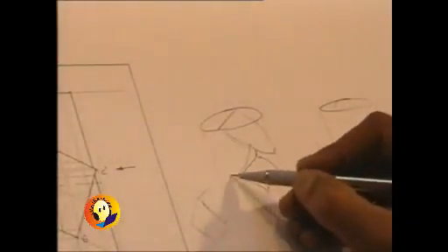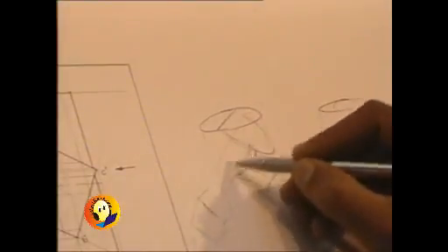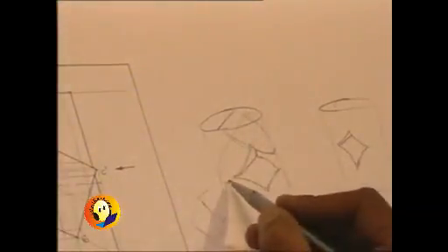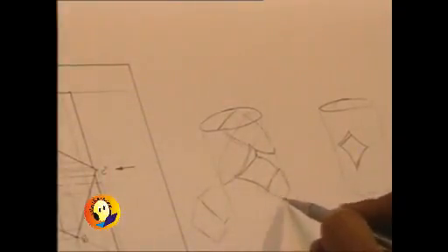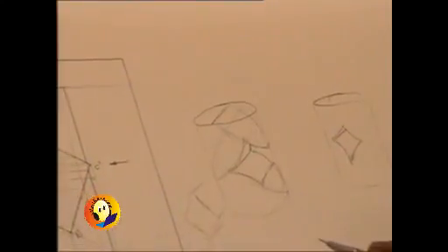There could be another section which is an ellipse, and so that part of the ellipse will be over here. This is going to be another section, which is again the section plane which will form the ellipse or the parabola, and these are the sections which are forming the actual shape which we are getting as the curves of penetration. The square prism would have been present. The figure will appear like this.